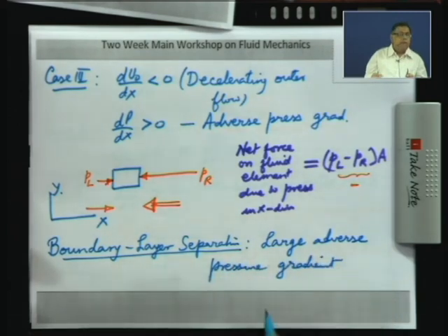Now, unfortunately, if the boundary layer separates, the boundary layer approximation is not valid beyond the separation point. So, all this idea of Prandtl of dividing the flow field into two regions and making two different approximations in the two regions will fail. However, you can use it to predict roughly the location where the separation takes place.